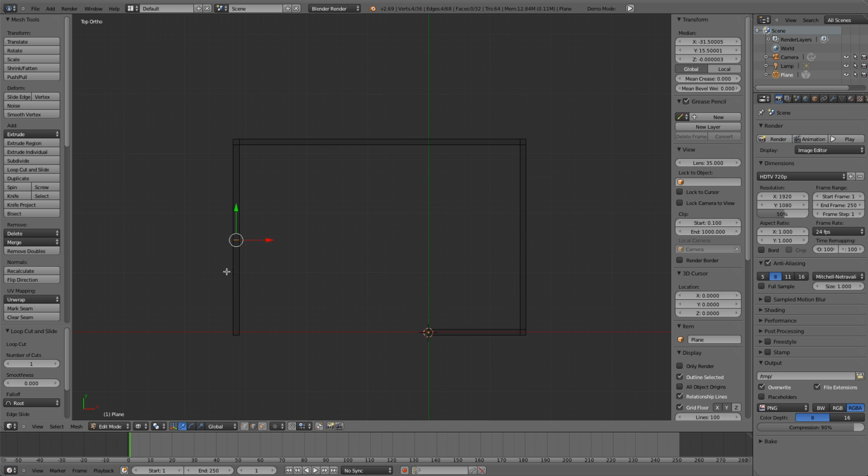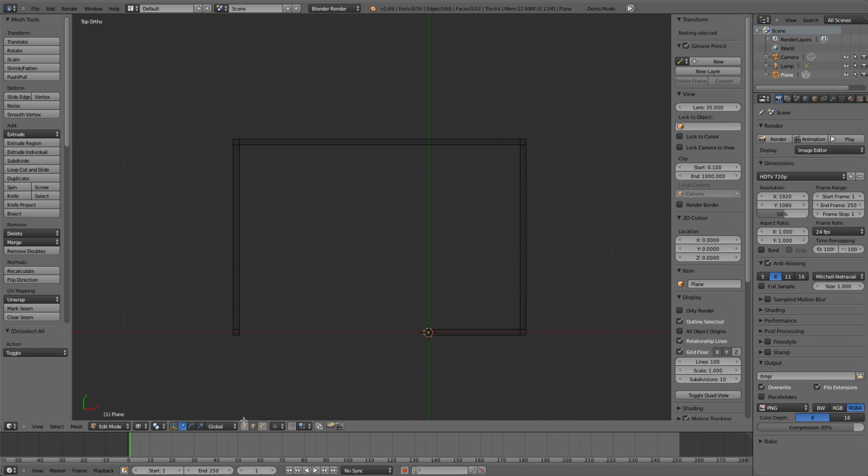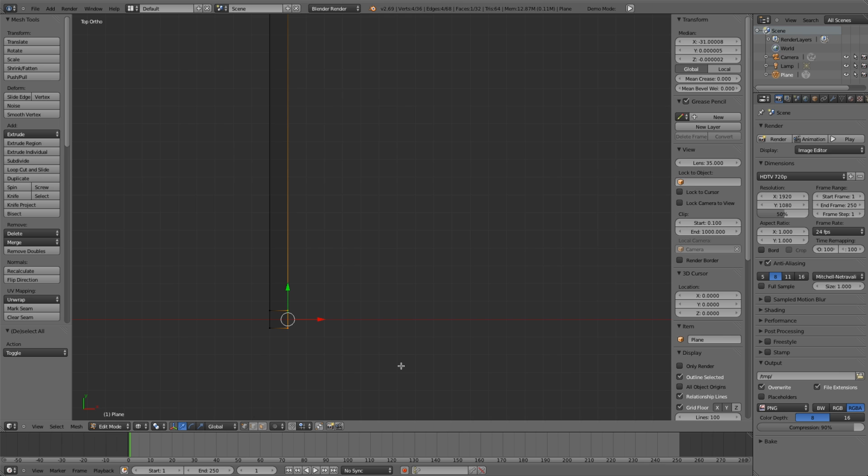Then in the properties panel, we're going to go underneath the median tab, and change the Y value to 0.5. Again, make sure it's global. Next, we're going to hit A to deselect all the edges, then B, and then select the bottom right 2 vertices. Press E to extrude, and then -15. So this creates the perimeter for our castle.